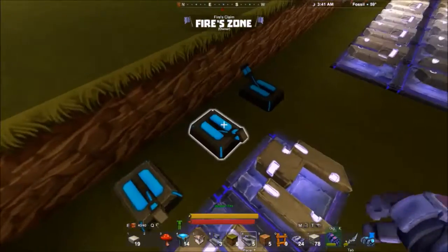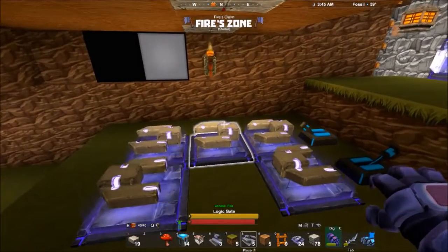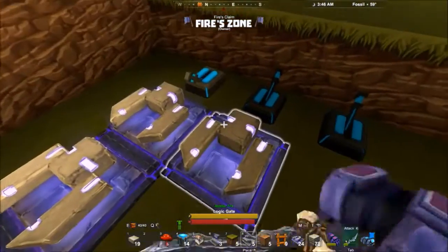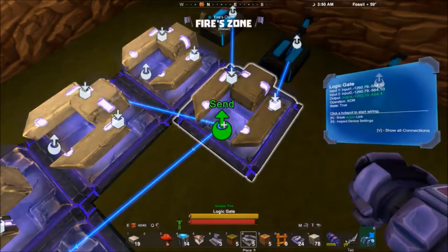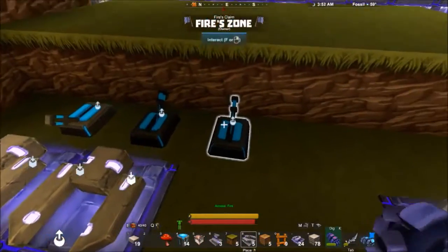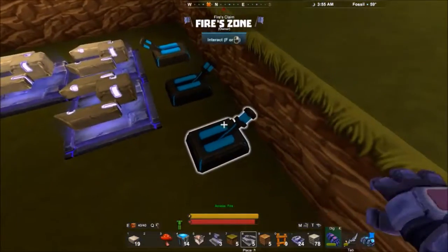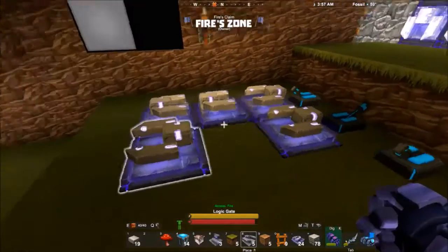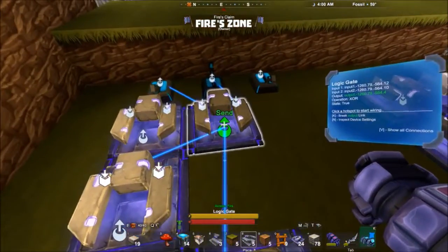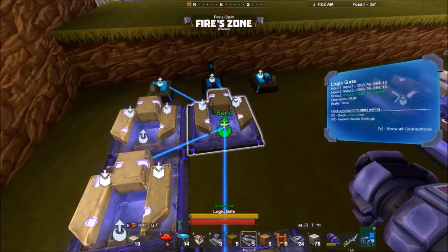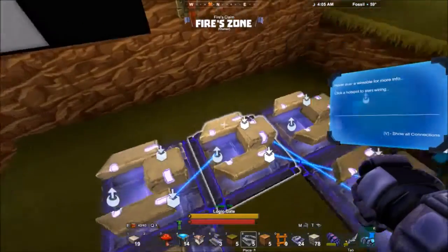So let's see an example. That's a 1, so this one right here is true. Consider this is true, so we have this one connected. If I put this one to true, this AND gate will be between this exclusive OR gate, which is true, and the carry, which is true. So this one will be true.